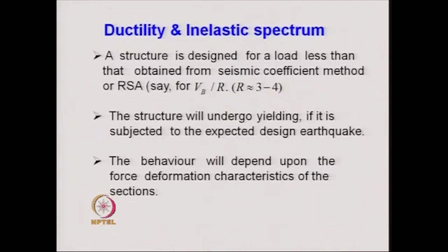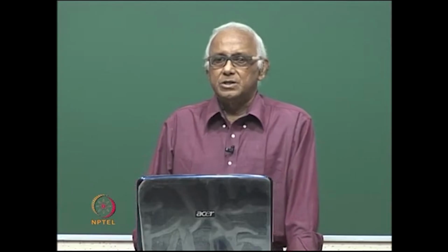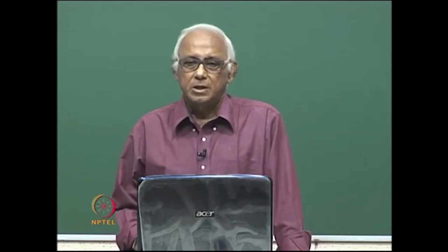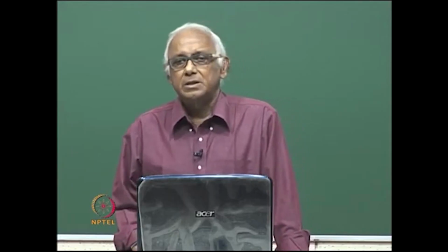Because of this reduction factor, a reduced load is acting on the structure, and we analyze the structures for that reduced load. As a result, in the case of the actual earthquake, all the structures that we design undergo inelastic excursion, that is, they go beyond the yield limit. Different elements go into the yield limit to different extents, and therefore there is a specific ductility demand imposed on the structure, not as an overall ductility demand, but a ductility demand which varies from element to element.